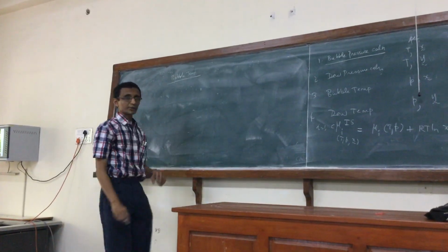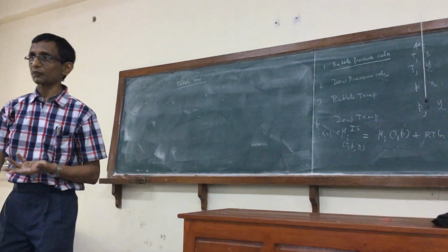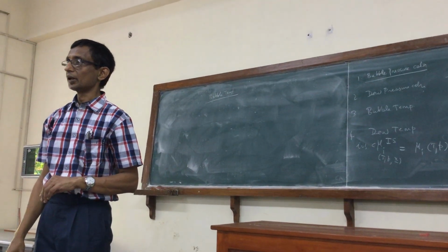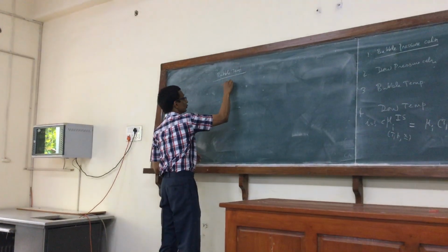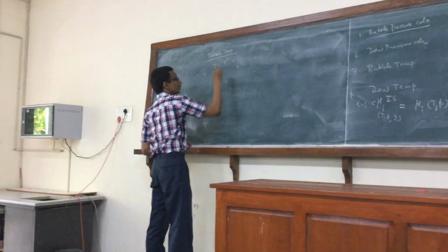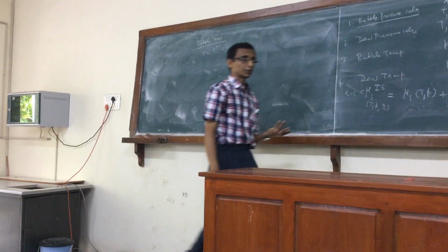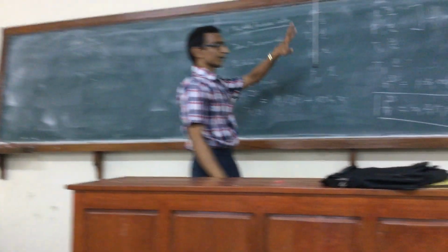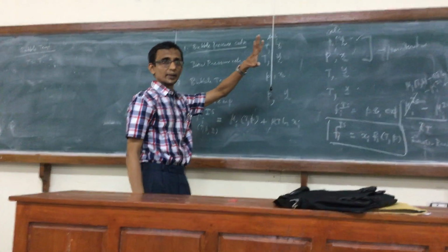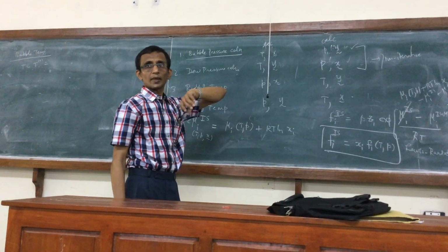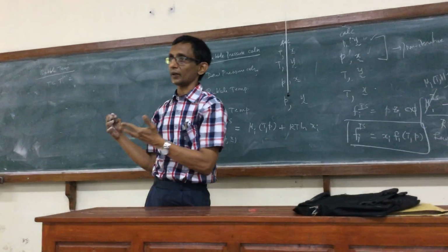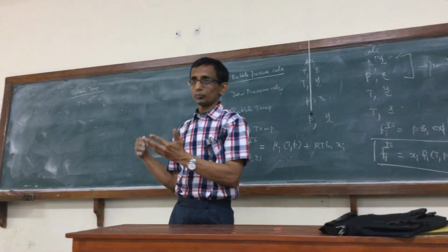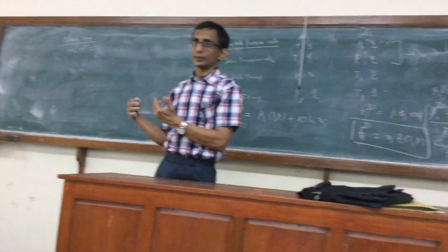First I see the temperature is not known and there seems to be no direct way of finding it. So T has to be assumed. So we take T to be equal to... What we will assume is open to question. But since these are ideal systems, and typically if you see, even for the binary case, the boiling temperatures will lie between the two pure component boiling temperatures, right?